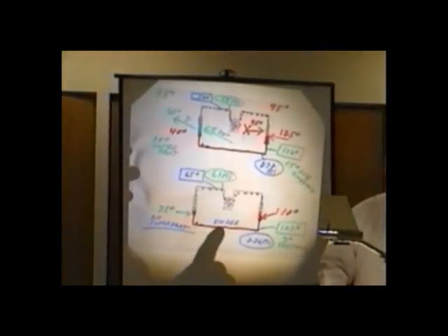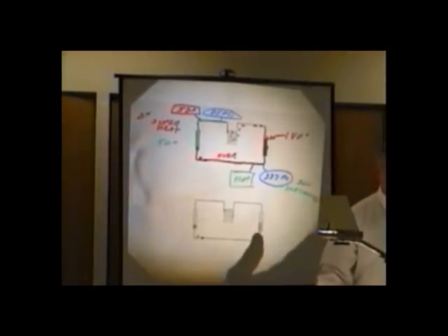Normal. But if it's undercharged, subcooling goes down. Superheat goes up. Overcharged, subcooling goes up. Superheat goes down. Got that? We okay? Yes. Now we get into diagnosis. I didn't say this stuff was easy. Now the restriction. That's right.